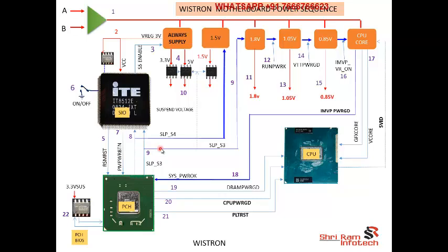When it turns on, it waits for 20 milliseconds. When it sends out this signal, it waits 20 milliseconds to receive this signal. Within the 20 milliseconds, if it does not receive the system power okay signal, then it turns off all the signals. You getting my point? So it turns on, then turns on next, and receives the acknowledgement, that is system power okay. Once it receives that system power okay, that means all your power streams are okay.